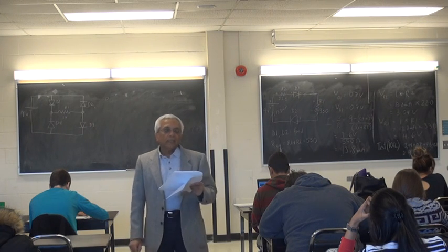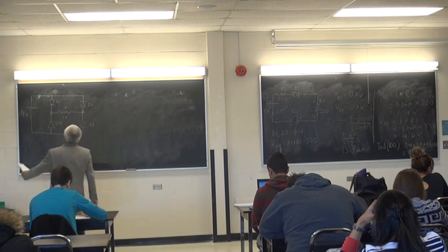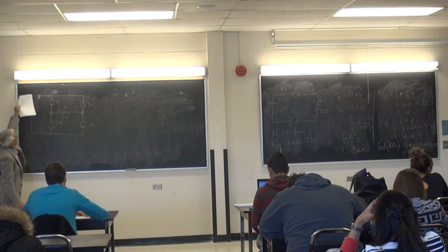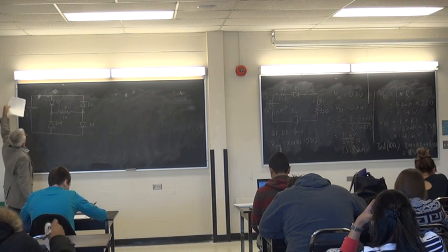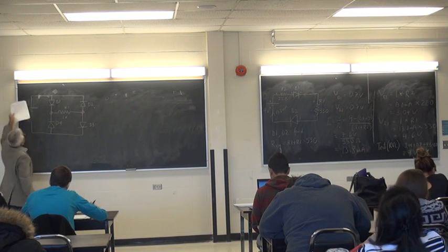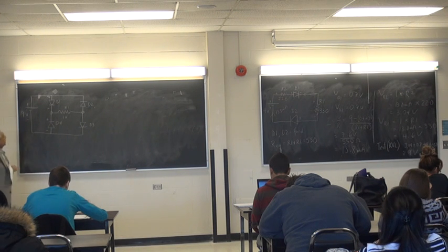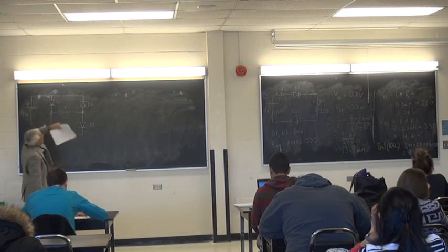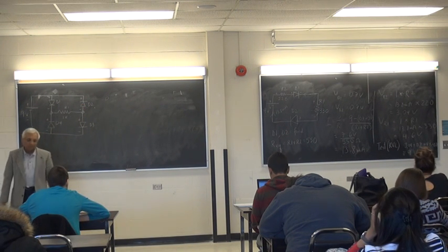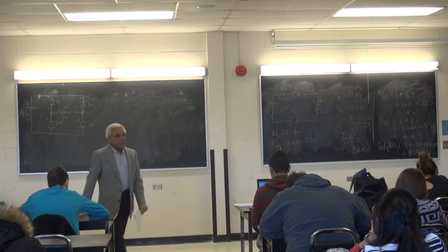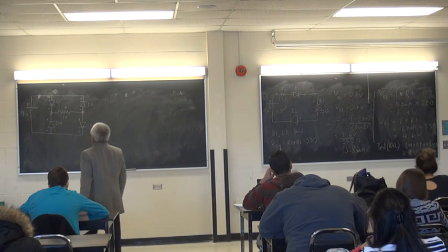So right away, I start putting the pluses and minuses on the circuit. So here's my supply. It's going to cause current to flow. So as far as polarity is concerned, here's plus minus. So it would be plus here, minus, plus here, minus. You see that? On the other side, same idea. Plus, minus, plus, minus. That will tell me which diode is forward biased and which one is reverse biased.